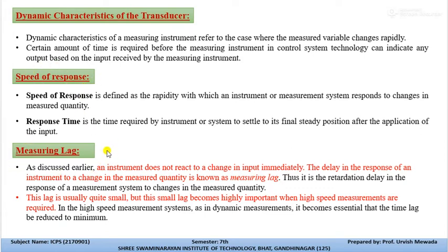Now the second is measuring lag. In measuring lag, the instrument does not react to a change in input immediately, or offers a delay in expressing the measured quantity. The delay in the response of the instrument to a change in the measured quantity is known as the measuring lag.